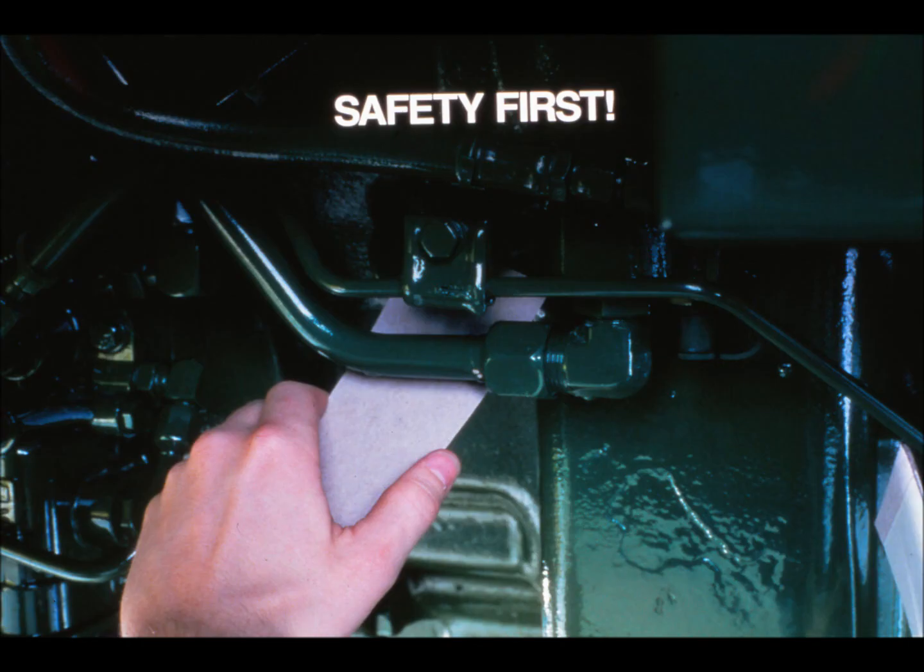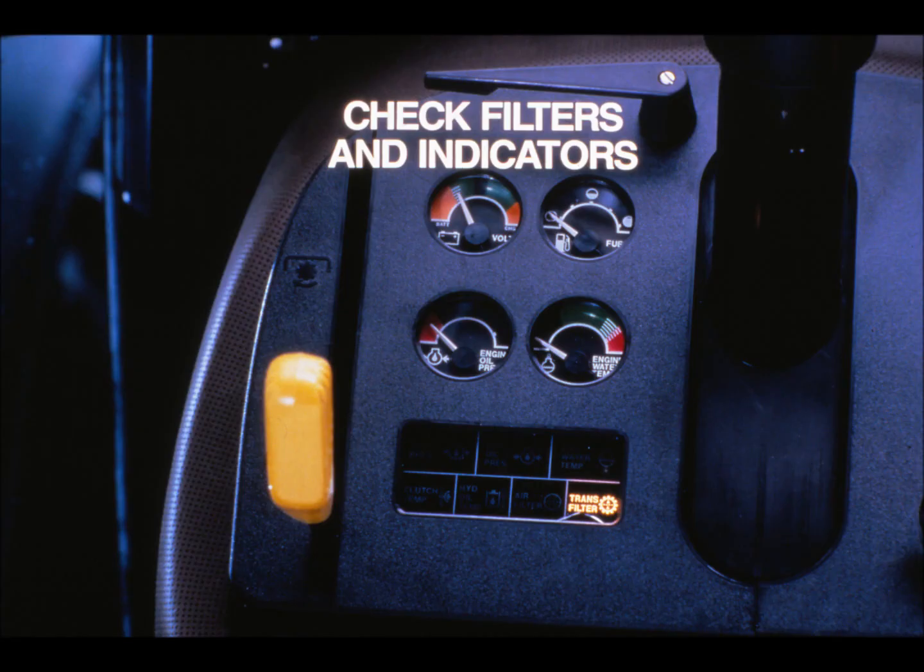Use a card or piece of paper to check for leaks. Do not use your hand. High-pressure oil can penetrate the skin and cause serious injury. Next, check the oil filters and make sure the warning indicator system is functioning properly. On tractors with filter indicators, check the indicators first. On tractors without indicators, check the filters. The diagnostic procedure gives you a series of steps for performing checks on the indicator circuit.